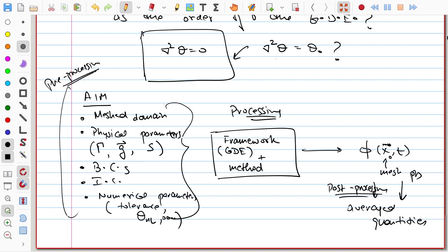Okay, so it's on a loop. You can see that as time proceeds, we start to see this circulation develop. In fact, on the top also we get some circulation, which was not expected. Okay, so you can see CFD can actually give us insight into this flow situation, and in this case we are also plotting the u velocity, so we can find out at which point the separation happens. And flow separation can have a lot of effect on the mixing inside the flow and so on. So you will be able to do this by the end of this course, right? And you will be able to write this code yourself.